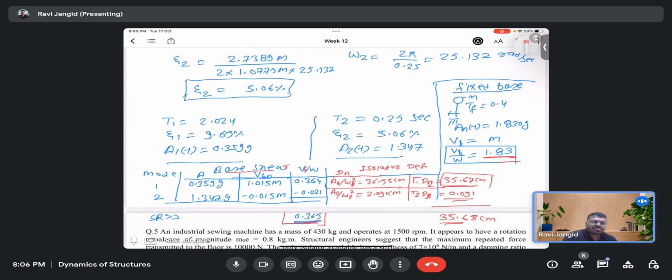Yes, that will happen. Suppose you have a 3 degree of freedom system, then you have three frequencies. You apply the frequency from 0 to 50 on that system, get the response, and plot it. At those three frequencies you will get the peaks.